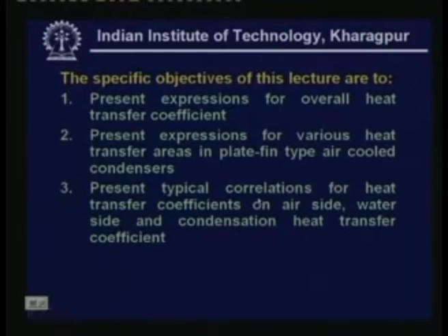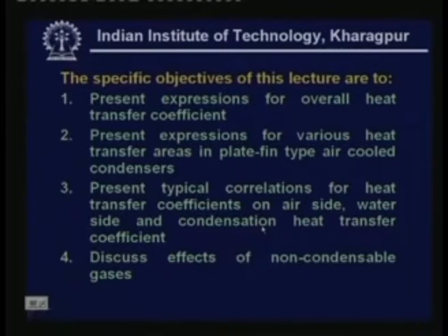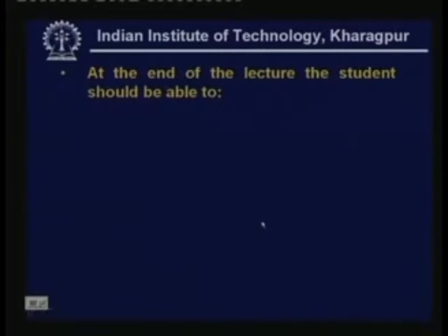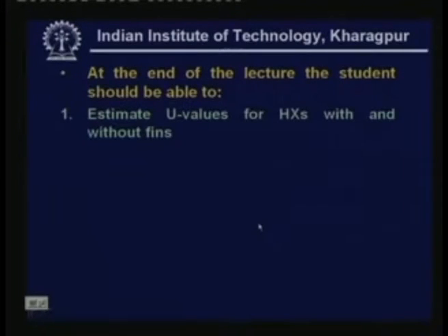Welcome back. The specific objectives of this particular lecture are to present expressions for overall heat transfer coefficient, present expressions for various heat transfer areas in plate fin type air cooled condensers, present typical correlations for heat transfer coefficients on air side, water side and condensation heat transfer coefficient, and discuss effects of non-condensable gases.